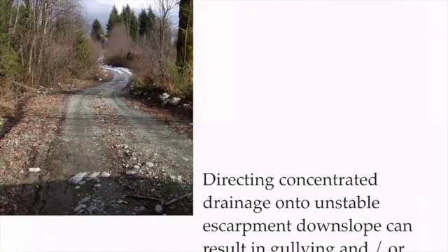In some cases, you look at a road surface and think, oh, that road looks okay. This is the Dakota Creek Road, and it has 300 meters of road without a culvert. Sometimes you can get away with that and not have an effect on water quality, but in this particular case, there's quite a bit of water generated on the up road side, the left side of the road. This runs down in the inside road ditch, crosses the Dakota main line, and runs for 200 meters across a very flat glacial fluvial terrace, and then abruptly flows over the 20-meter escarpment and creates this huge gully.